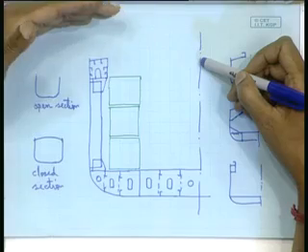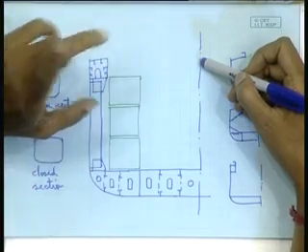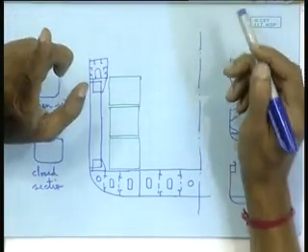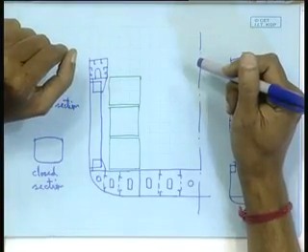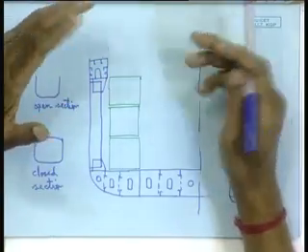From the functional requirement, we will have to have a huge hatch opening. From functional requirement, we had wing tanks in bulk carrier. From functional requirement, we had lower deck in general cargo ship, right. Why lower deck? Because for segregation of cargo. In general cargo ship it's called a go anywhere type of ship. So it can carry any cargo to anywhere, any place.